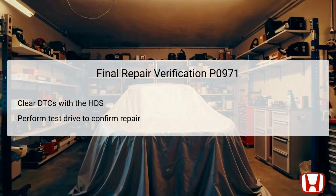Following this, it's vital to perform a road test to confirm that the vehicle operates correctly and that no further issues arise. During the test drive, attention should be paid to the operation of the transmission and any related symptoms that were initially present. If the MIL remains off and the shift position indicator functions normally, it suggests that the repairs were successful. Clear documentation of this verification process will aid in maintaining the vehicle's service history.